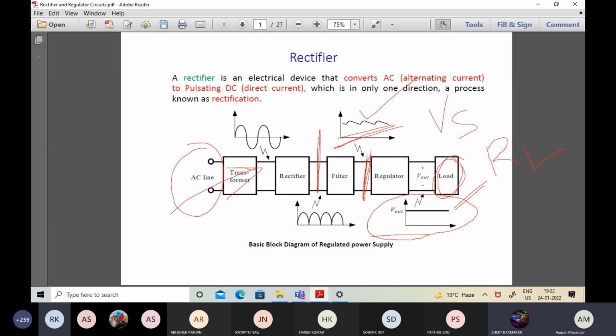What we can say is that, to a certain extent of variation of the input source voltage as well as the load resistance, a change in the value of V out can be encountered. Accordingly, the regulated DC power supply is working perfectly even if there is a variation of Vs or variation of RL or both, as long as V out is not changing too much. That is basically called regulation. Now this regulator circuit that we are referring to is designed making use of Zener diodes.